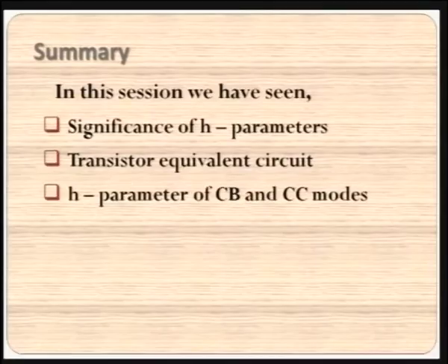Migrating from one mode to another mode is also possible using the H parameter. So, I have concluded the H parameter concepts with this lecture, and we will see the session summary of today's lecture. In this session, we have seen the significance of H parameters and the transistor equivalent circuit, and then the H parameters for CB and CC modes, and how we could migrate from one mode to another using H parameters.